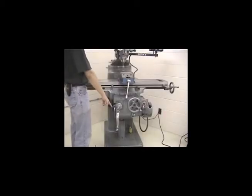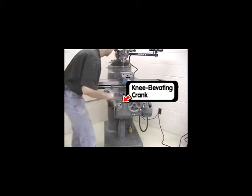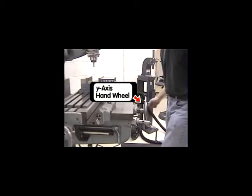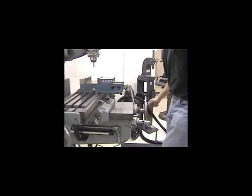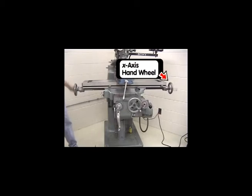3 wheels or hand cranks control the position of the table. The knee elevating crank moves the table in the Z direction. The Y-axis hand wheel moves the table forwards and backwards in the Y direction. The X-axis hand wheels move the table left and right in the X direction.